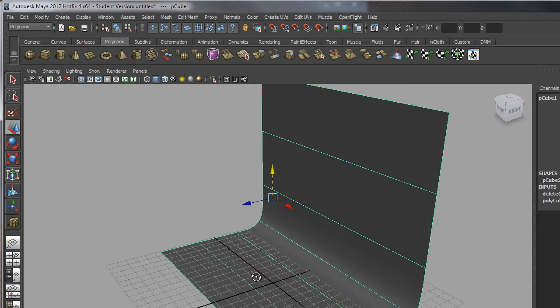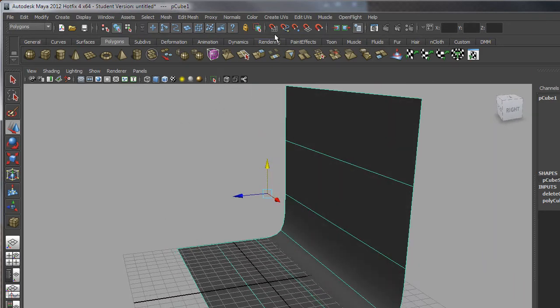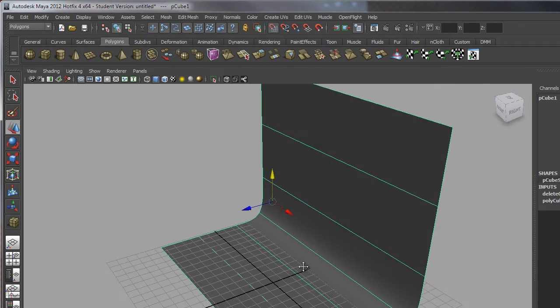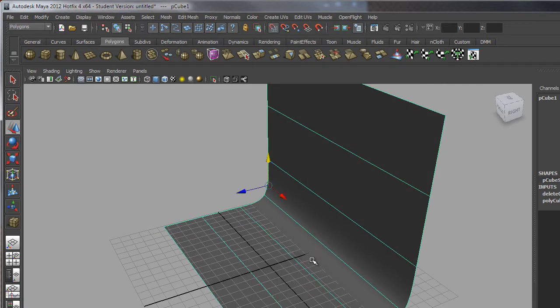So what we'll do is we'll turn on snap to grid just here, and that's the X key. If you hold down X, you can see it toggles this on as long as you're holding the key down. So if I hold it down and let it go like this, you can see it turning on and off. What we want is to just switch it on. Okay. The next thing I'll do is hold down the D key.